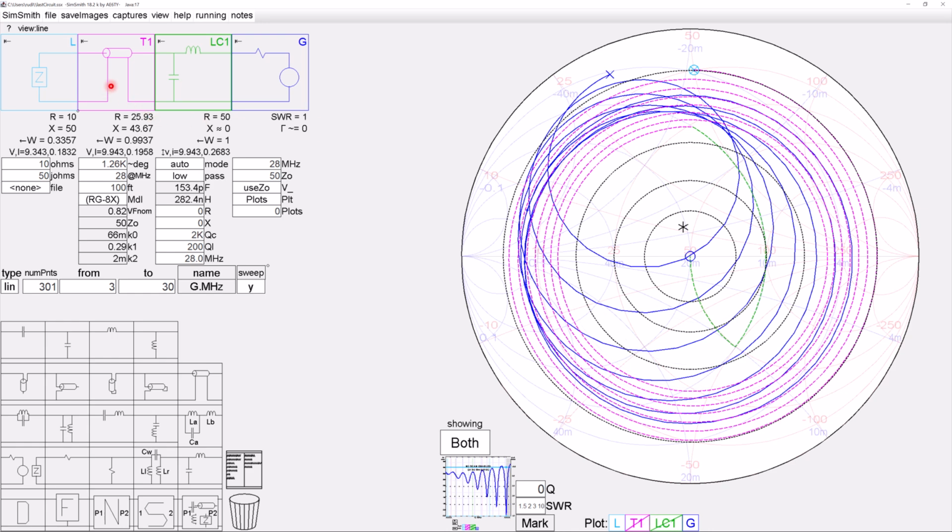If now I move the tuner to the rig end with 100 feet of coax with the same load, I'm down to 33.5% power. I lost 66. I lost 2/3 of my power this way. So you can see how sensitive this is to coax length, because the coax is in the middle of your resonant tank circuit between the tuner and your antenna. And yes, the coax is the primary recirculating loss in both directions, forward and reverse power going through your system, recirculating here.